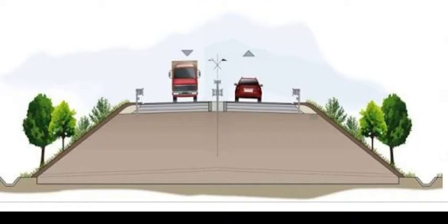This embankment is very important in case of high flood level. HFL is near the ground, or the highest water table is towards the surface. If any major water bodies are nearby, then we cannot construct the highway at the ground level. Then there is a need for a highway embankment.